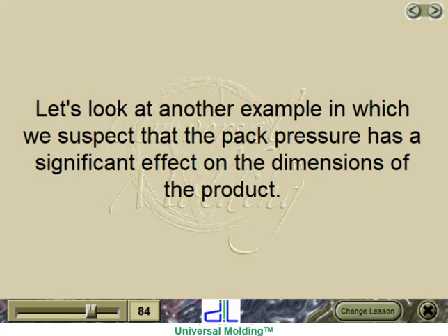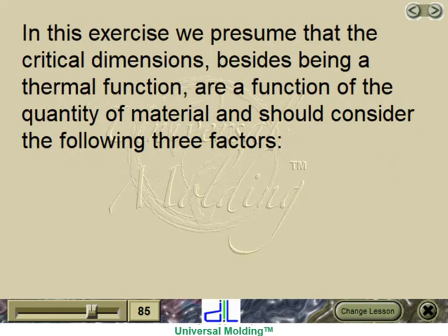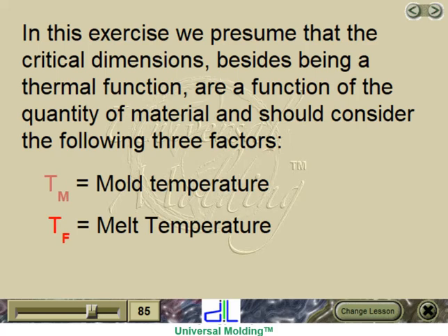Let's look at another example in which we suspect that the pack pressure has a significant effect on the dimensions of the product. In this exercise, we presume that the critical dimensions, besides being a thermal function, are a function of the quantity of material and should consider the following three factors. T sub m equals mold temperature, T sub f equals melt temperature, and P equals pack pressure,